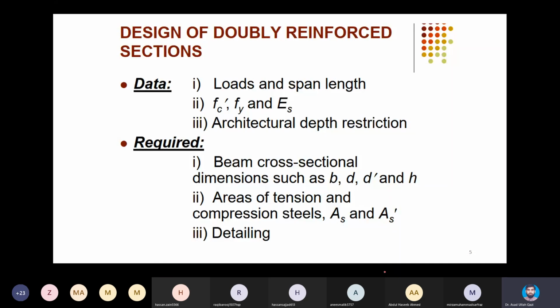Just like other design problems, as a structural engineer, when you are asked to design the beam, you will be given the architectural working drawings. The architect will tell you about the dimensions of the room sizes, the story heights, and the permissible clear story height. He may have some concern on the beam depths, so he may point out that you should not go beyond this much depth below the slab. Because of HVAC ducting, heating, ventilation, air conditioning ducts, a provision for false ceiling and the requirement of clear story height, there might be some concern on the beam drop below the slab.